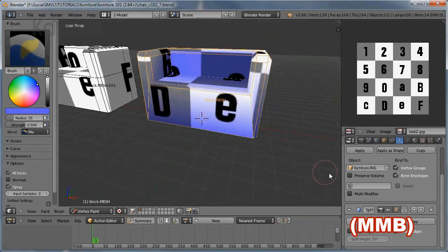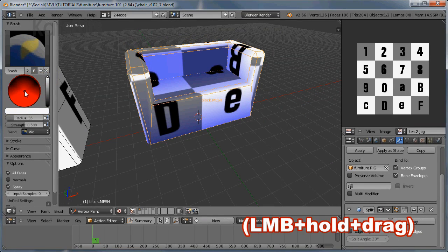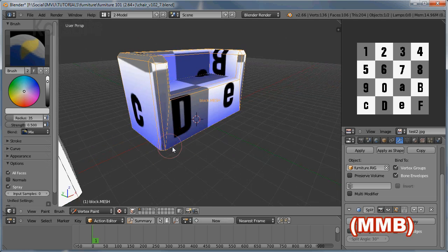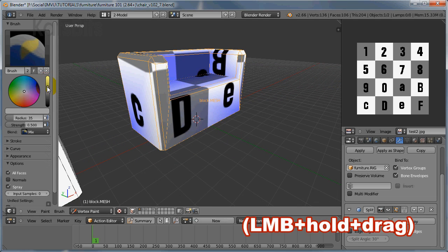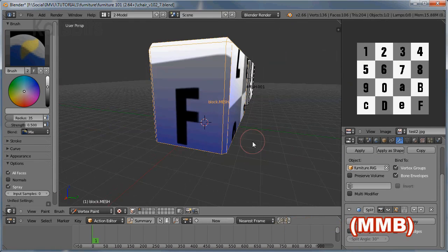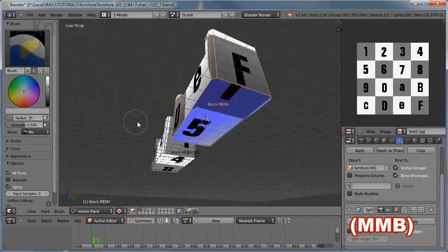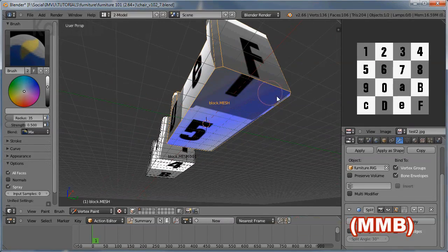Or alternatively, we can tint the mesh with black and white or grayscale shading to give the impression of shadows where areas of the mesh wouldn't otherwise be fully illuminated. Doing this eliminates the need to use complicated textures where shading or shadows are baked into them.